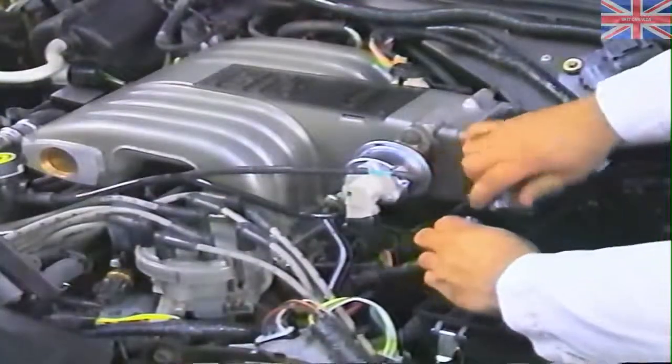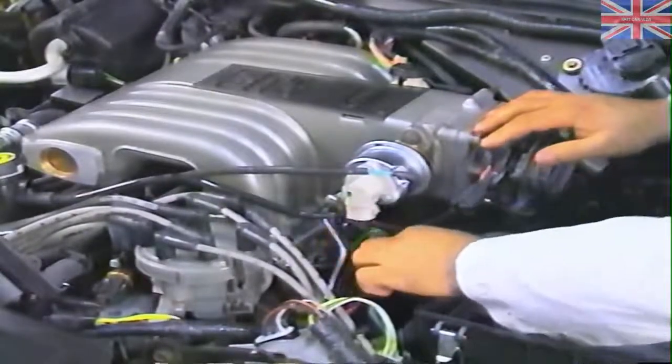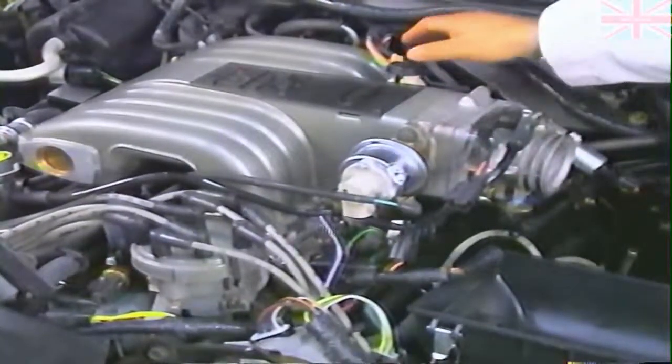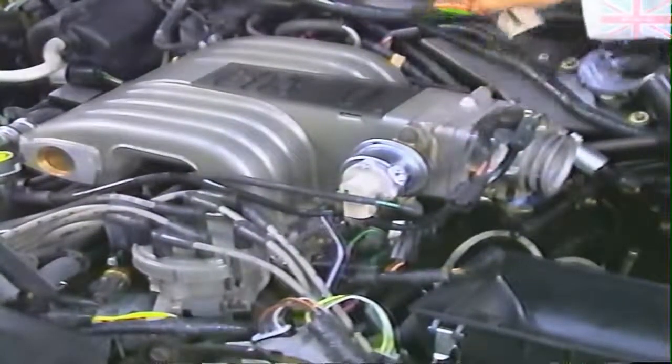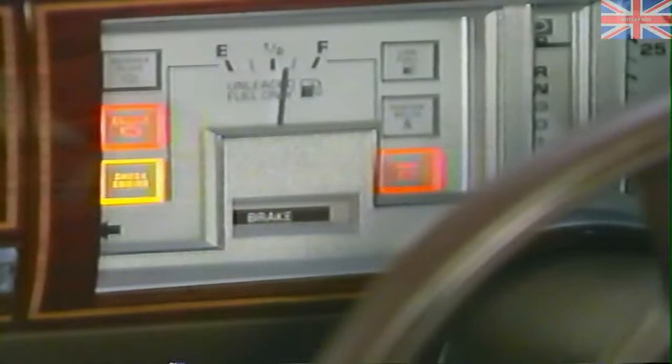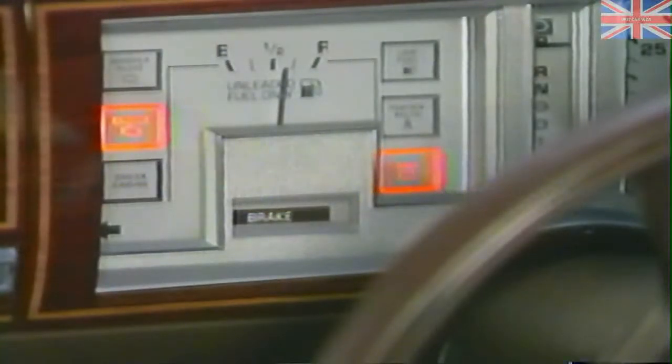Adaptive strategy allows the computer to make modifications for wear and age of the engine and other components. It has the ability to learn. This adaptive strategy also functions with another modification called FMEM, Failure Mode Effects Management. Whenever the engine is in this mode, a code 98 will display. The KAM, Keep Alive Memory feature, allows the computer to retain diagnostic code information when the vehicle is shut off.